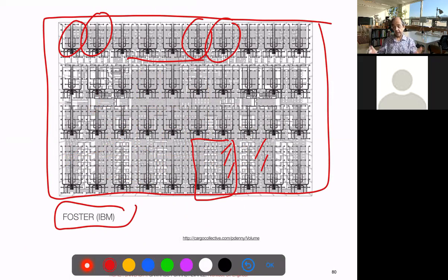But in this large area, it makes a lot of sense to decentralize those areas to have smaller plants and more independence in regulation by teams or areas. So maybe some part of the building is working and another is on holidays. Maybe some of them need hot and others need cold in other areas. So you have a lot of possibilities, even though the space is very wide.